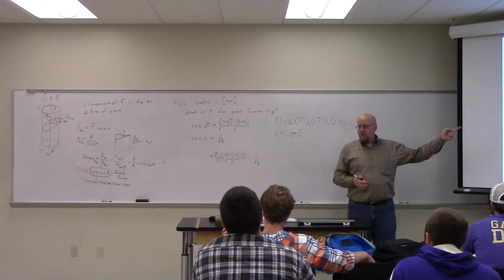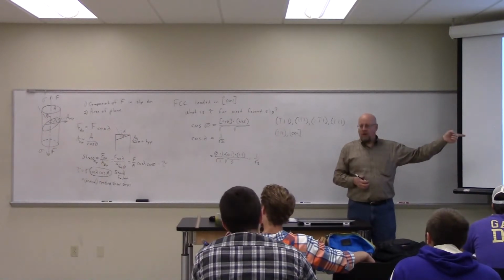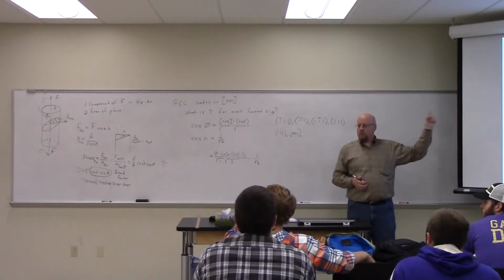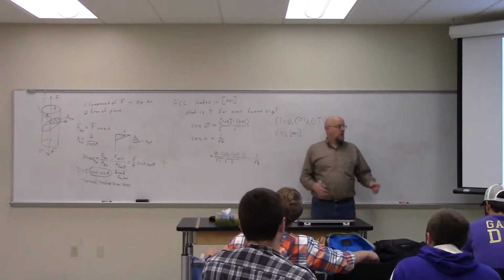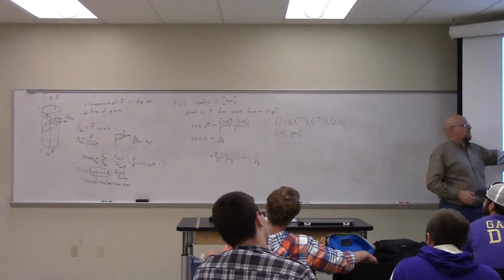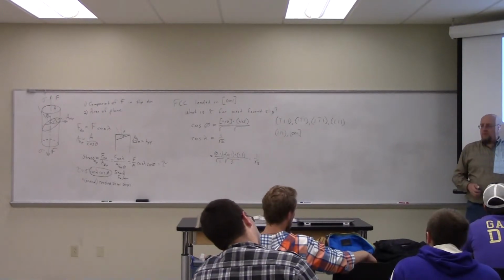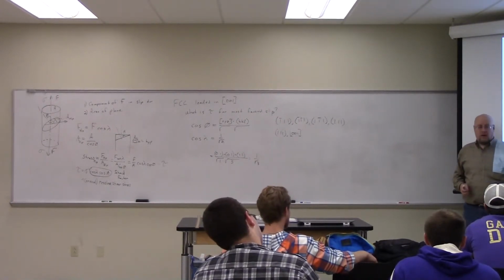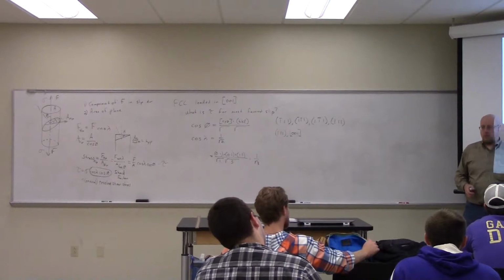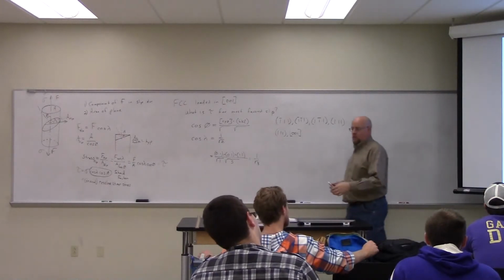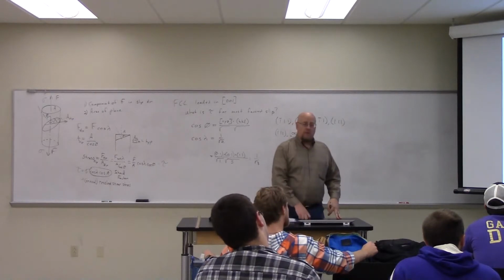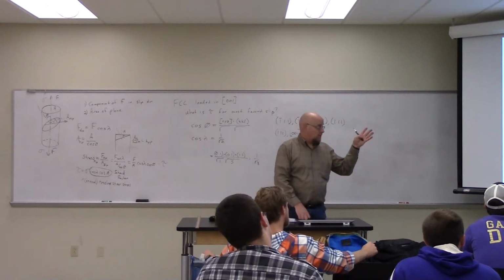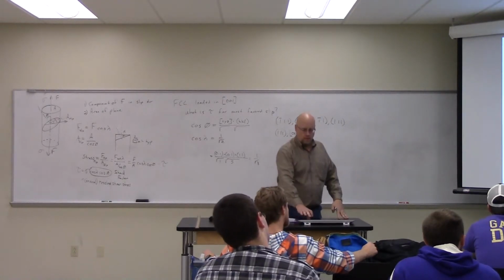By definition, the slip direction is in the plane, so all the lambdas are going to be 90 degrees. Doesn't matter which direction we're talking about, and the cosine of 90 is 0. So if I pull this in the 1, 1, 1 direction, this set of slip conditions is absolutely not active. I will not get any slip on that blue plane if I pull it in the 1, 1, 1 direction. However, I will get slip on that direction, in that plane.